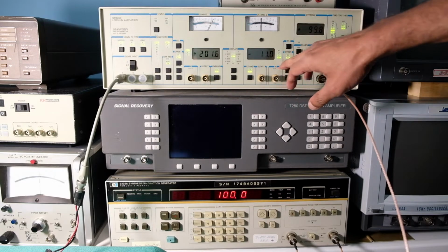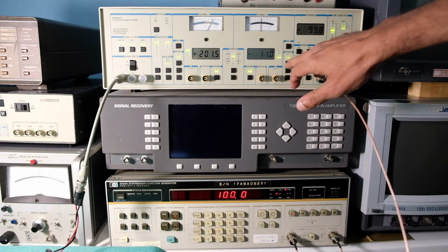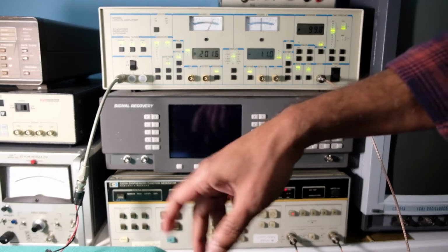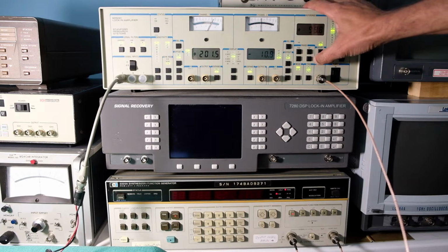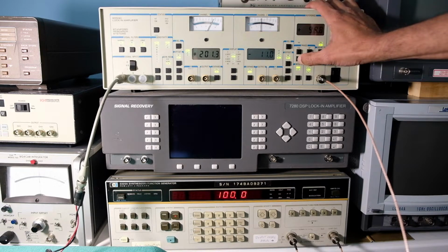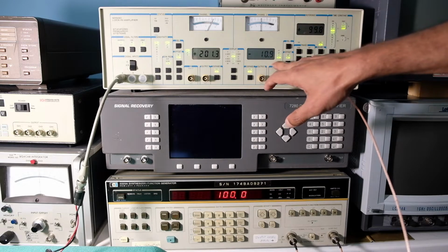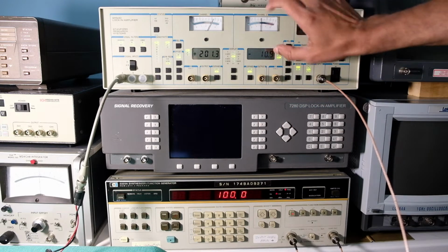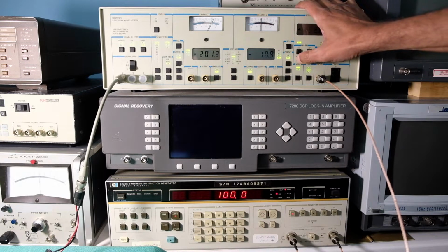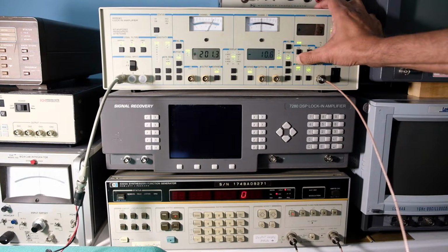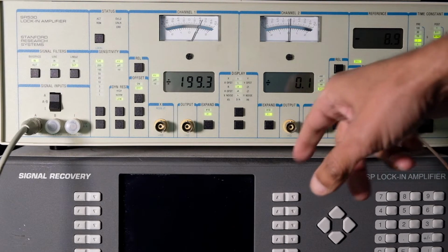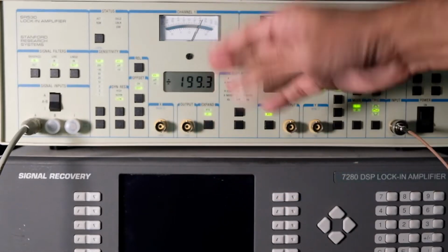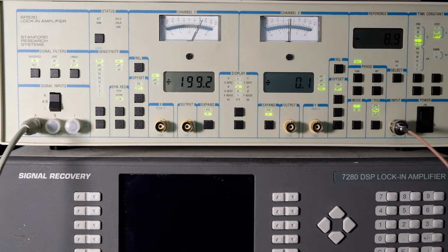Before I start the measurement, I want to zero out the phase, so make sure that the reference clock and the signal are in phase. So to do that, I'm going to align. This is right now showing 10.9 degrees of phase difference, so I need to make that 0. I can do that by reducing this phase by 10 degrees. Okay, now you can see that the phase is close to 0.1. Amplitude is 199.3 millivolts, and those two numbers look good.